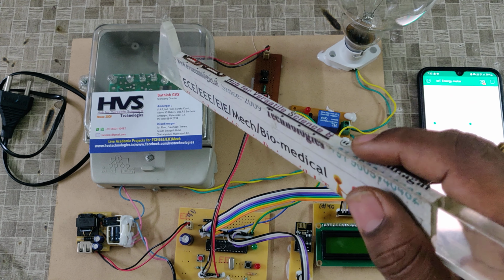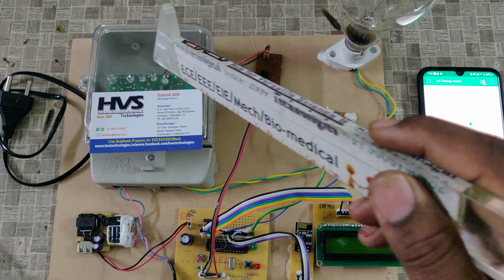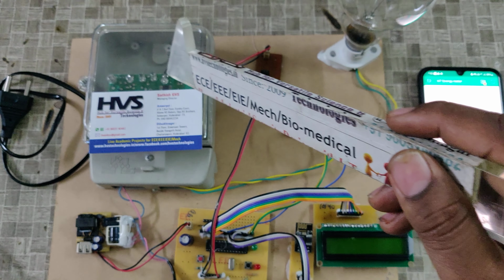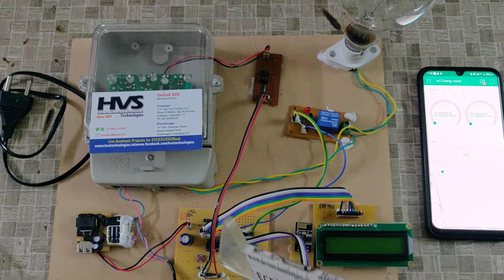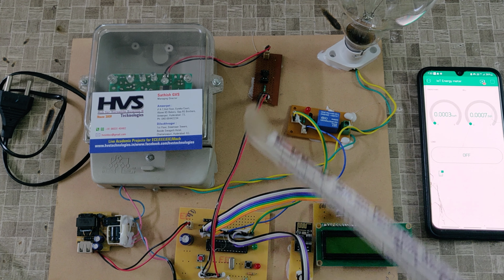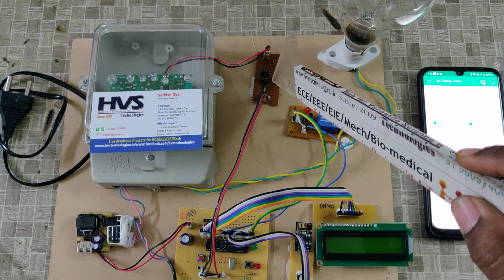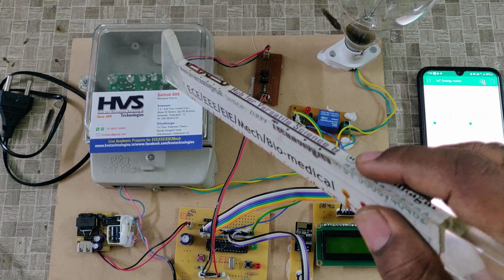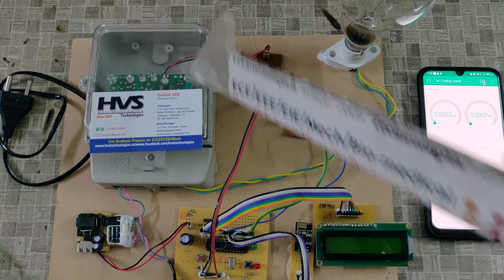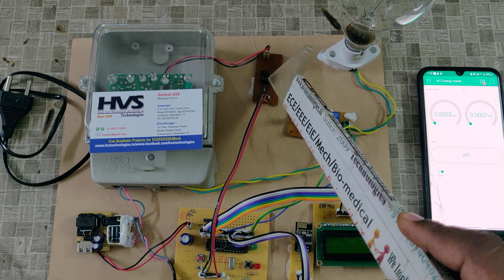We could provide the LED output directly, as we are getting DC only. But if any short circuit occurred in this board, the microcontroller, which is the main controlling motherboard, may get damaged. So in order to protect the controller, we place the optocoupler, which is an optically coupled connector between the LED and our microcontroller. If anything goes wrong, only this IC will be damaged and we can simply replace it.